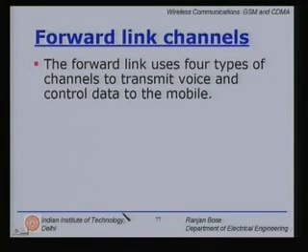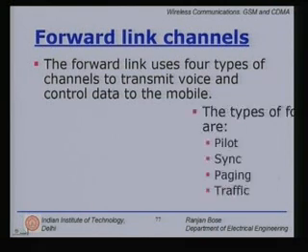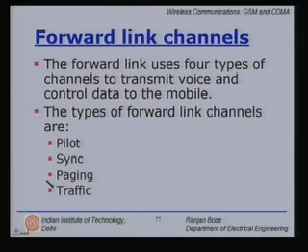First, the forward link channels. The forward link uses 4 types of channels to transmit voice and control data to the mobile. Please remember, forward link implies base station to the mobile. The types of forward link channels are pilot, sync, paging, and traffic. As the name suggests, all 4 are meant for different purposes.